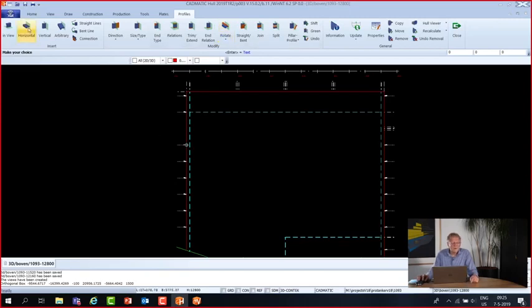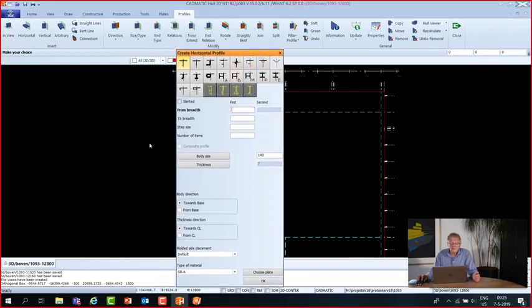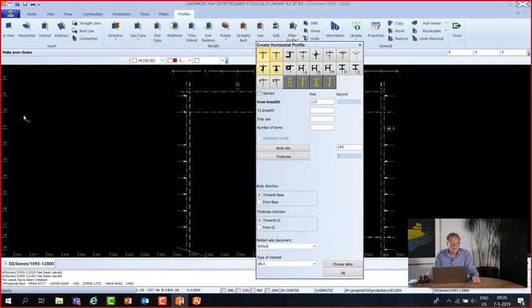I want to create new ones, horizontal ones, bulbs again, but now 140 times 7 millimeters. I could enter a value from centerline here, but unfortunately I forgot about it, and to make it easier I can press key number 2, and then a kind of transversal framing system is shown on the left side of the window, and I will use these.